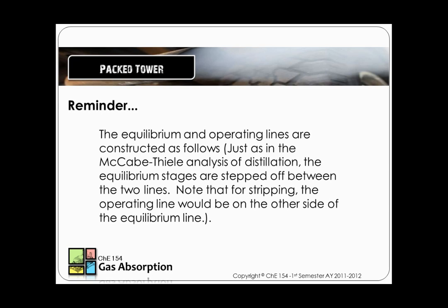For packed towers, we should be reminded that the equilibrium and operating lines are constructed as follows. Just as in the McCabe-Thiele analysis of distillation, the equilibrium stages are stepped up between the two lines. Note that for stripping, the operating line would be on the other side of the equilibrium line.